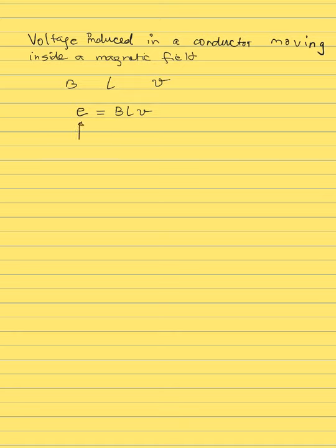That's the amplitude again. The induced voltage is E, measured in volts. B is the magnetic field density, with units of Tesla or Weber per meter square. L is the length of the conductor in meters, and V is the velocity in meters per second. If you do not have a moving conductor, then the voltage will not be induced, or it requires something else. And this V is the relative speed of the conductor. We're looking at the amplitude E equals BLV, and the polarity of this voltage will be defined by Fleming's right-hand rule.